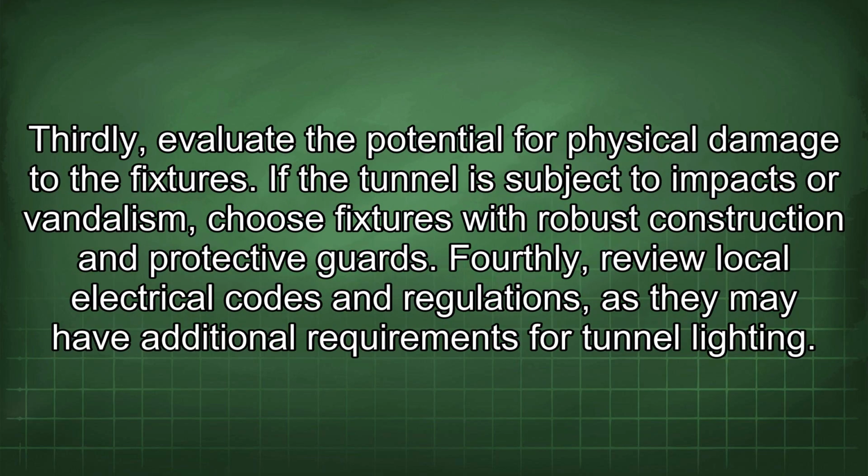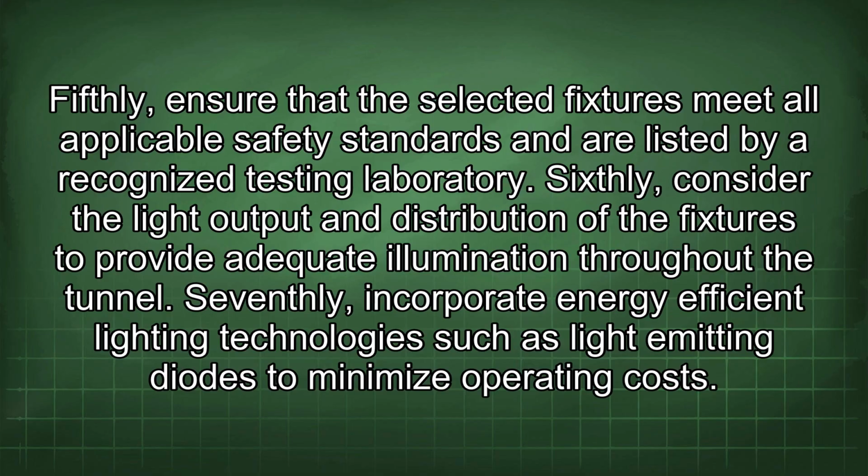Thirdly, evaluate the potential for physical damage to the fixtures. If the tunnel is subject to impacts or vandalism, choose fixtures with robust construction and protective guards. Fourthly, review local electrical codes and regulations, as they may have additional requirements for tunnel lighting. Fifthly, ensure that the selected fixtures meet all applicable safety standards and are listed by a recognized testing laboratory.